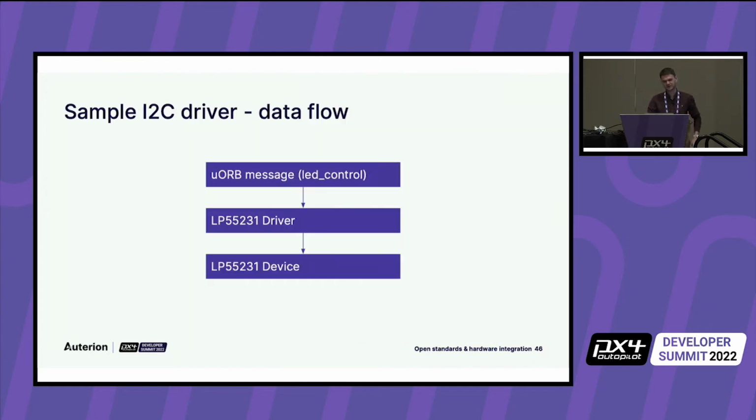Drivers in PX4 are actually quite simple. You probably know that we have uORB, and uORB is this pub/sub system, so you can publish data and subscribe to data. And all the internal communication within PX4 runs over this uORB pub/sub system, right?